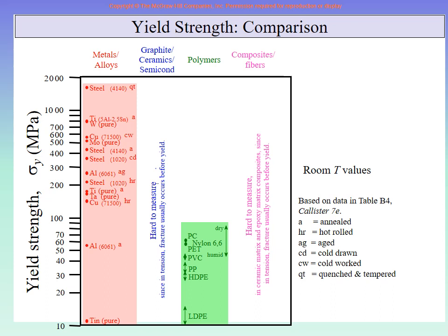If it is a strong ceramic material, then the strength is high. The line on the stress strain diagram goes up and up and up, but suddenly it finishes in a straight line. It does not go into the large deformation. So if it does not go into plastic deformation, there is no yield point. The end of the elastic region is there, but you cannot call it a yield point.